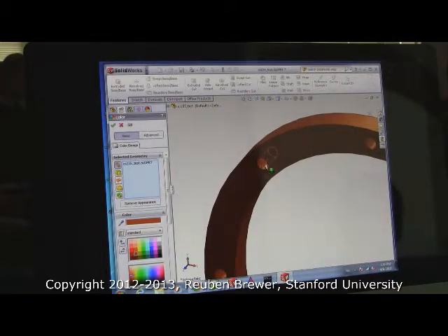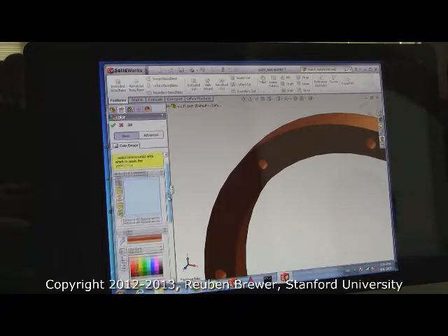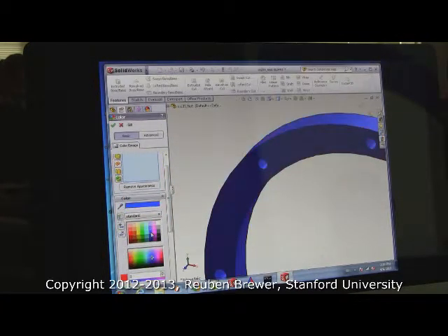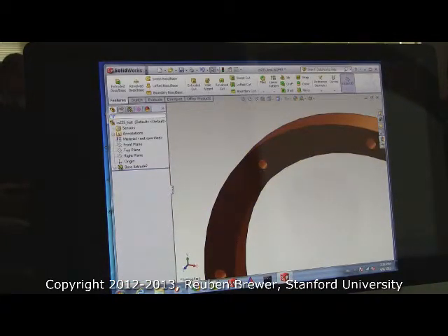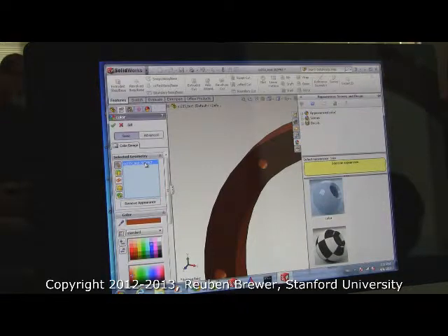So I'm going to zoom in here and select that hole and then hit blue. Now hopefully your whole thing turned blue, right? Did everybody's whole thing turn blue? Basically when you click on that part, it always selects the entire body. And that's bad. This is one of these little quirks I'm showing you. Do you see over here how it says CS Test 30? Delete that. Now hover over each of these little buttons: select faces, select surfaces, select bodies, select features, select part.